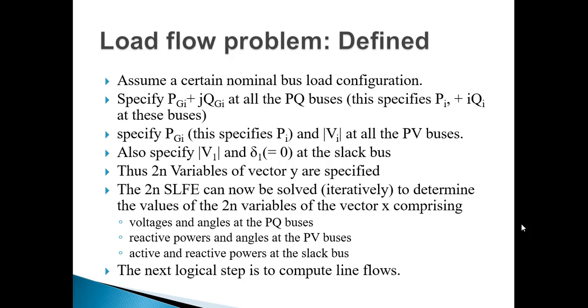So when we solve them, we determine certain vectors. We will determine the voltage and the angles of the PQ bus, reactive powers and the angles of the PV bus, and active and reactive power at the slack bus.